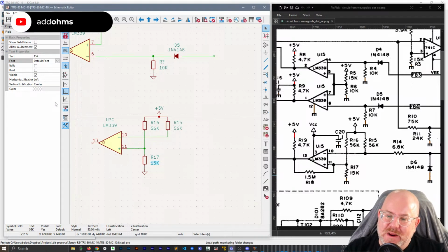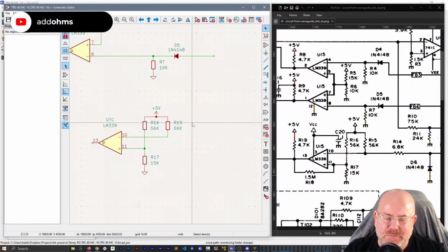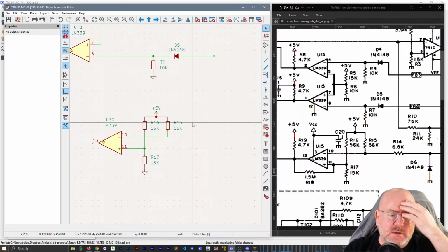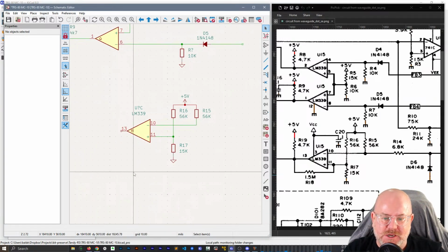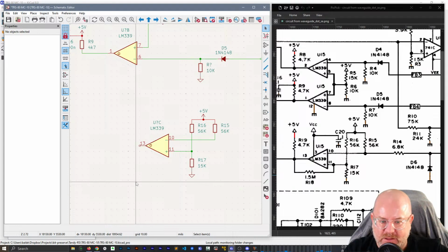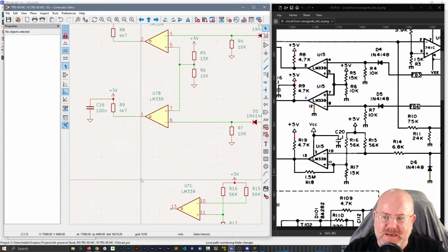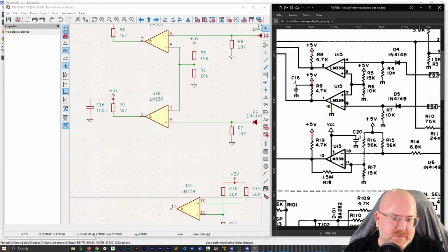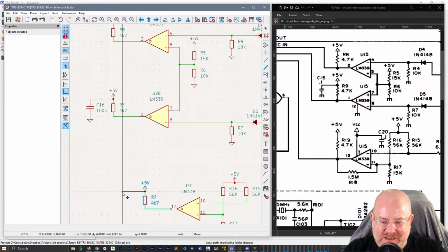It'd be cool to have that feature. Oh wait, it's already there. Somebody said something about how it would be nice if KiCad had a way to mass edit text objects in the PCB. I was like, well, it does. You can use the edit text tool, or you can just change the selection filter to text only and highlight all the text things. I don't understand why you're saying it needs to have that, because it does.